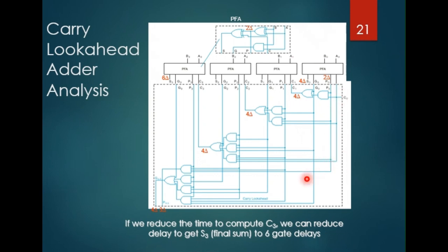In other words, some of you may have noticed, by using the new Boolean expression, now we make the generation of the carry out signal a parallel process, where it reads in the A and B that generate G and P, which are read in parallel, and get the C out signal faster. And you can see also, by having the advantage from the parallel logic, the small trade-off is that more logic is needed to make the parallel happen, so that the carry out can be generated in a shorter time.